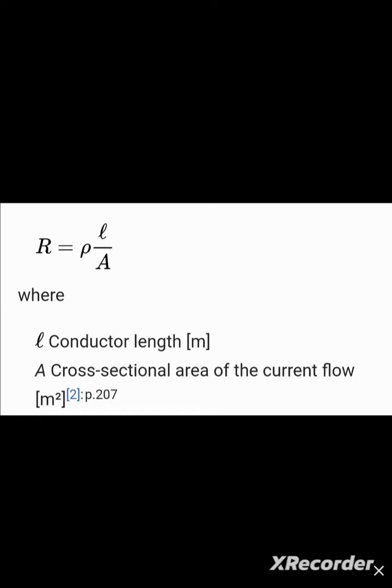So in metal, the piezoresistive effect is not profoundly observed. It is also there, but it is not profoundly observed. But in some special cases of metals, that change in resistance due to change in resistivity is more. But usually the change in resistance of the metal due to change in the geometry is often more.